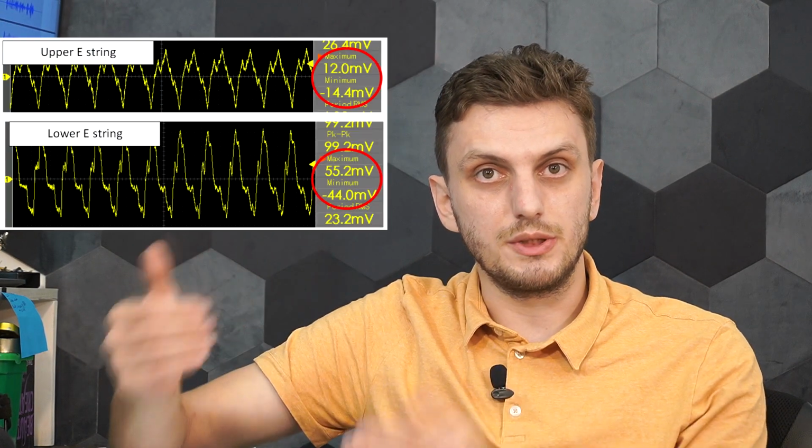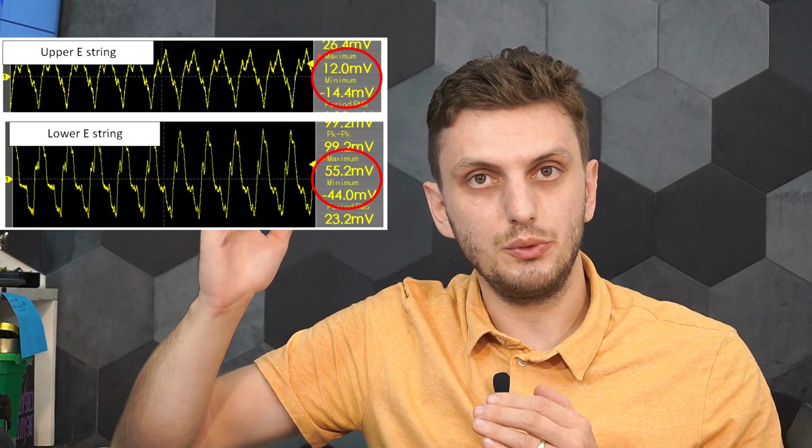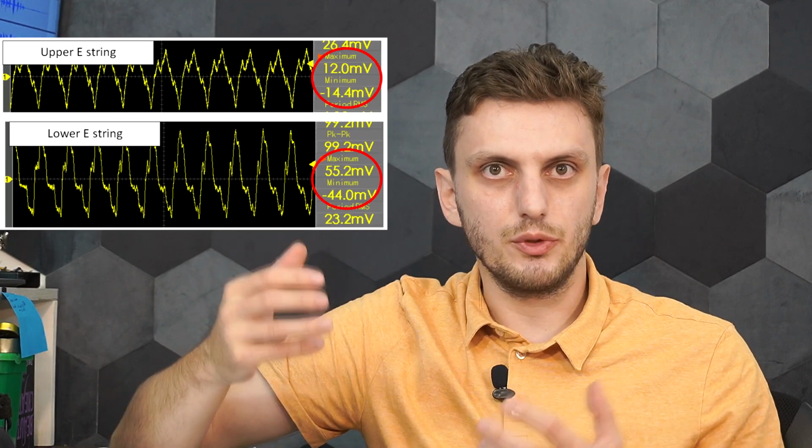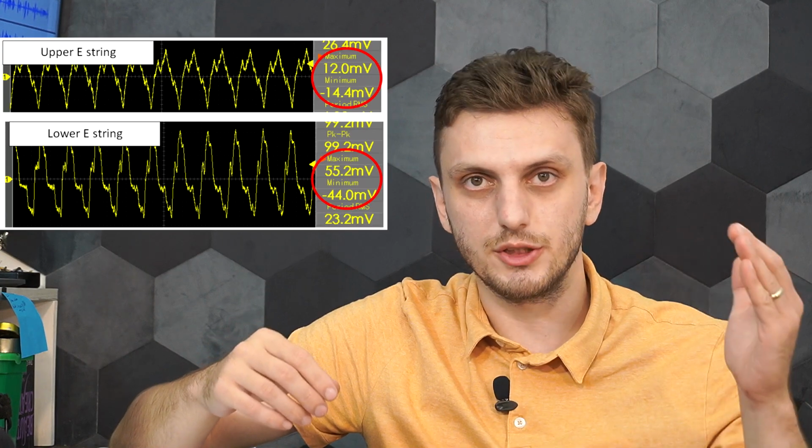Now, if you take a signal that's a combination of multiple other single frequency sine waves, you can end up with the case in which the two amplitudes are not equal. And of course, you will not know which is the highest amplitude, so you can't make a circuit that only looks at the positive or the negative amplitude. For our sustain effect, we will need a peak detector that can look at both peaks and then decide which has the highest absolute value and take that signal into account to adjust the gain. So let's look at how the circuit would work in a simulation first.